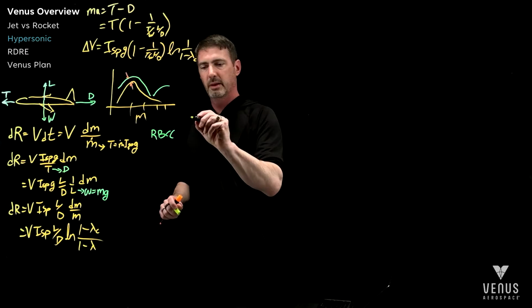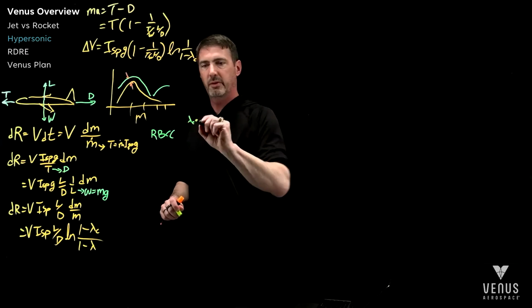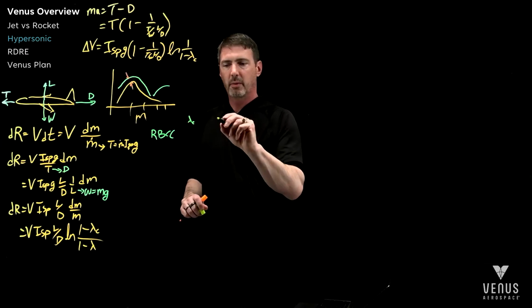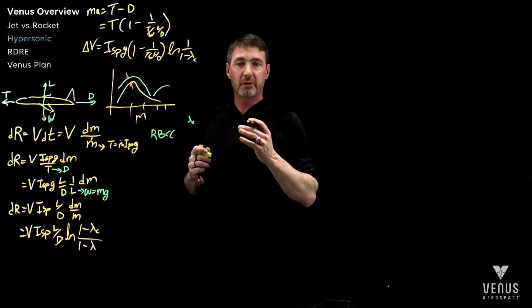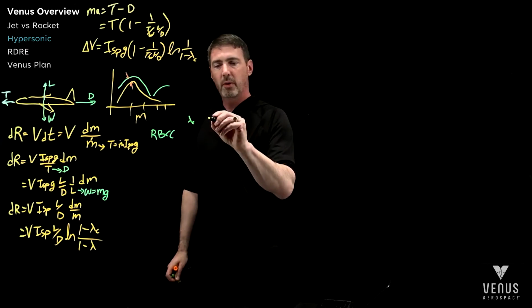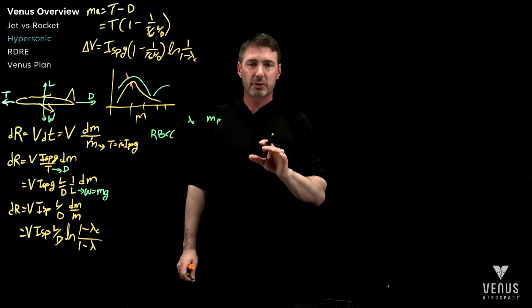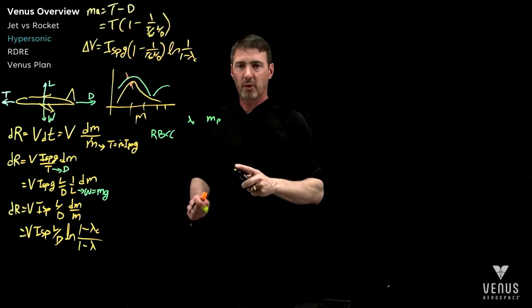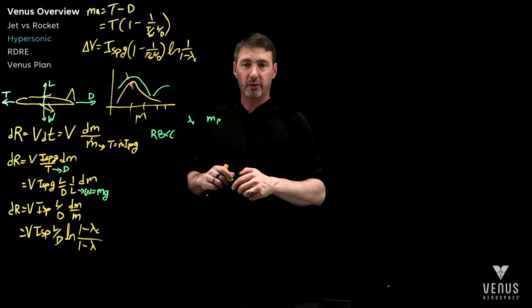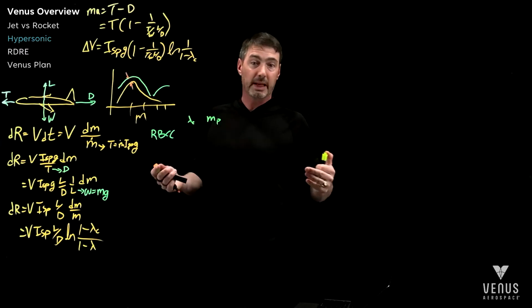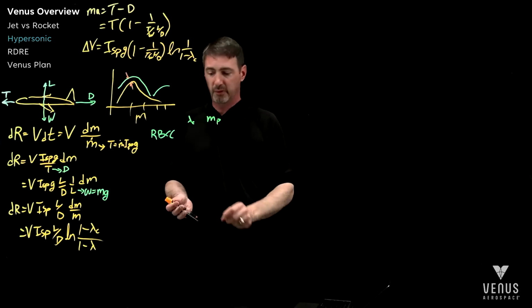I want to look at how much it takes to get to cruise speed. We want to look at this as a percentage mass of the system. We want to also account for the mass of the entire propulsion system. And then we'll look at the total stack up. This is your total propellant plus engine. So we can really compare the two.